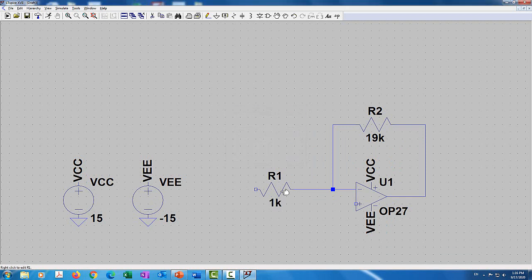So a couple of things when you pick those values, you have to be careful, because you know that there is a maximum current that flows out of the op-amp, there is a maximum current IO max. You shouldn't exceed IO max. If you do, then the op-amp departs the linear region. It's not going to work as nicely. So to do that, the resistors have to be bigger than, at minimum, 500 ohms.